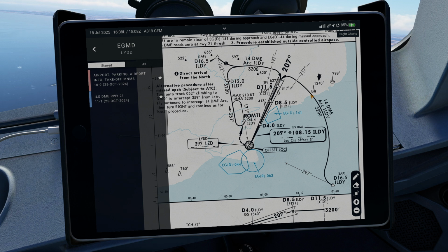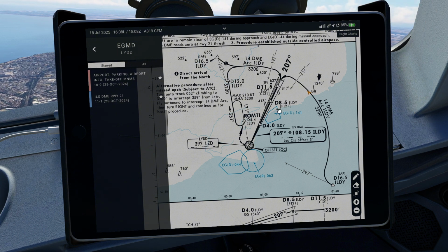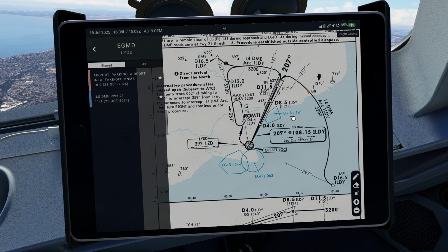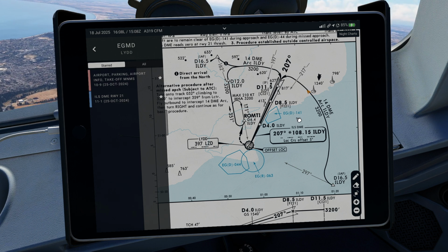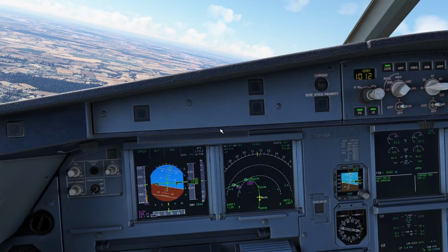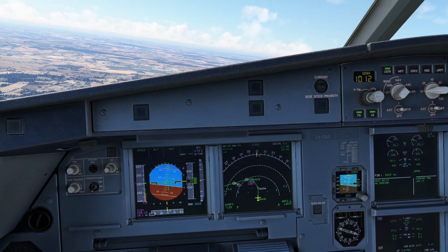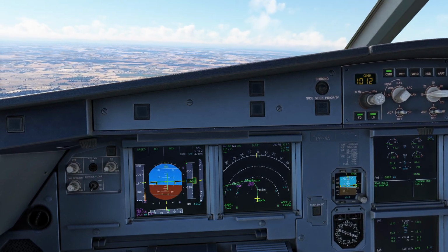And that's why, upon reaching almost 5 miles from the ILS on the approach, I will start the left turn to align with the runway center line, not sooner, because this danger area 141 is mentioned in the approach, and I observe these areas as a threat for this approach.